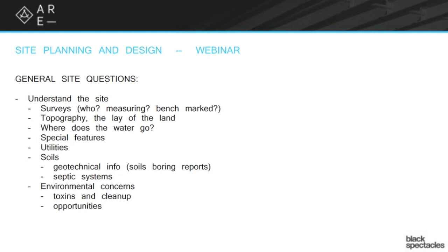And that's one of those things that shows up on a couple of different exams. And it's possible that it would show up here. So who does it? The owner hires that. When you talk about surveys, how do they measure in a survey? Decimal feet. Site plans are architectural, and they're done in architectural measurements. Surveys are engineering, and they're done in decimal feet. You sometimes see them in other measurement systems, but almost always it's decimal feet.